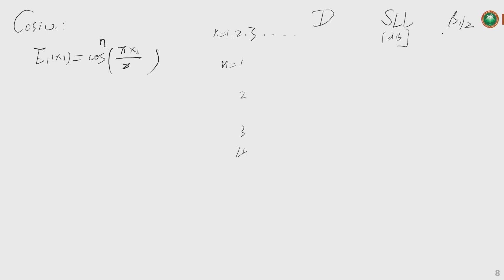So when we look at this half power beamwidth, previously when n equals 0, for example, that means this part equals 1 as a uniform distribution, right? For the uniform distribution the beamwidth is 0.88 lambda over Lx.